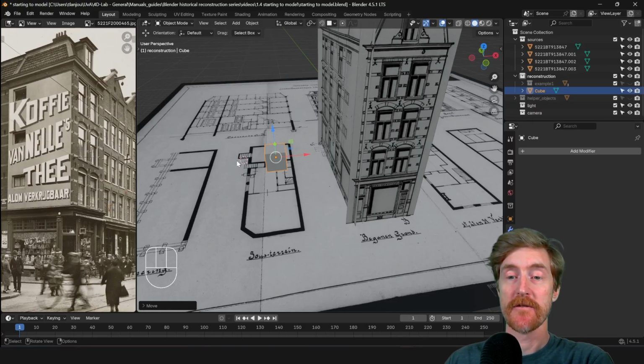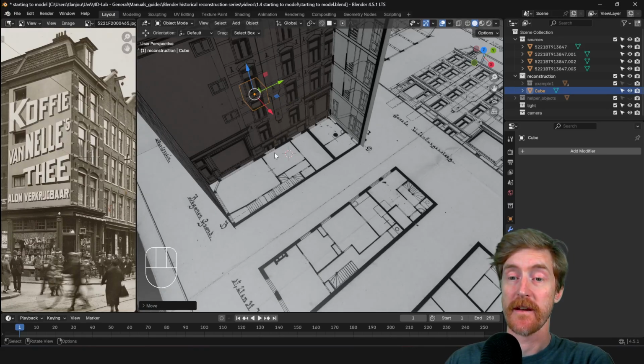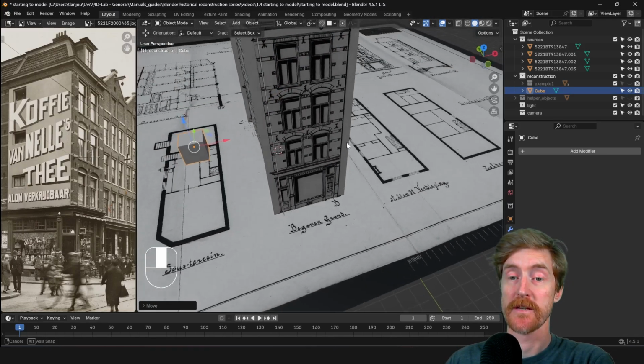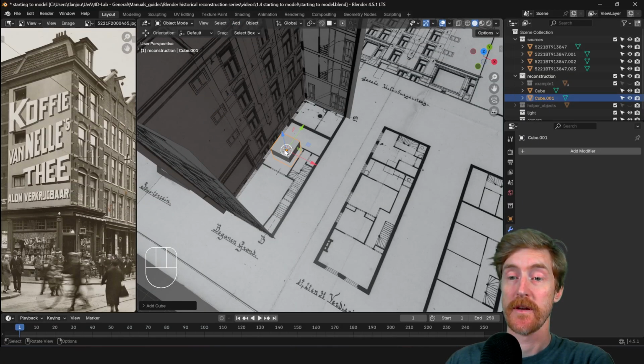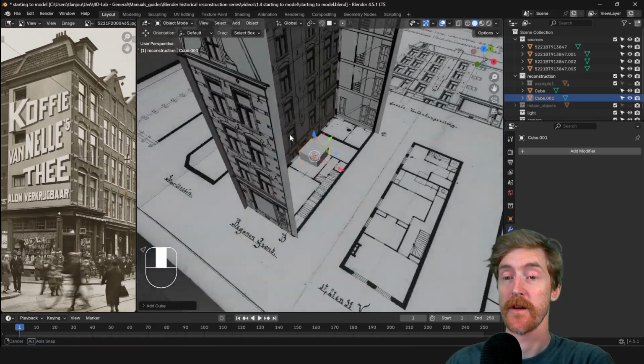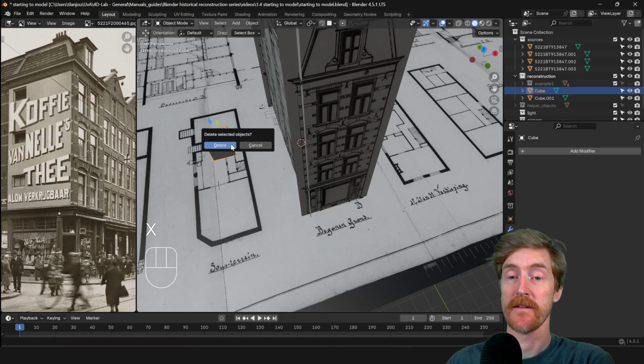I can easily relocate the 3D cursor by going to the place that I want my new object to spawn from. I hold Shift. You can see at the left part of my screen also what buttons I'm pressing. And then right click. Shift and then right click. And then the 3D cursor appears at a different location where you clicked. And then when I do Add, Mesh, Cube, it adds directly on the location that I want to have the cube. So I hit X to delete this one.